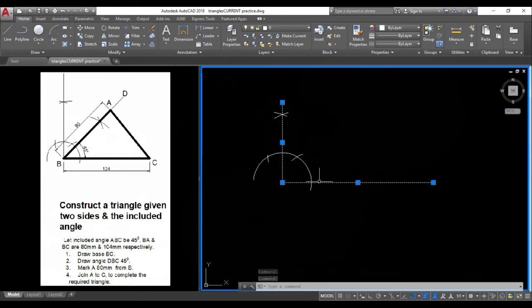To bisect this angle of 90 degrees into 45, we need to scribe arcs from this intersection here and from here where the arc meets both arms. So we are going to go to arc, and I'll use a radius of 30, and I'll just scribe my arc, and I'll repeat again from this point, 30, and all we need to do is to draw a line from the vertex through that intersection, and we know that that point is 80, so I'll hold the mouse there, type in 80 units, press enter.